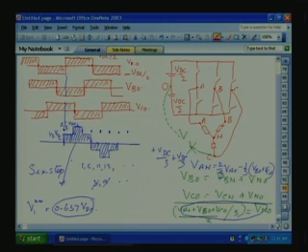This is the phase voltage waveform, VAN, 6-step, and it will have a maximum fundamental of 0.637 VDC. This you can do the Fourier series and you can find out. Now, with the 3 phase also like our single phase, frequency we can control by controlling the on duration, off duration of our pole voltages.